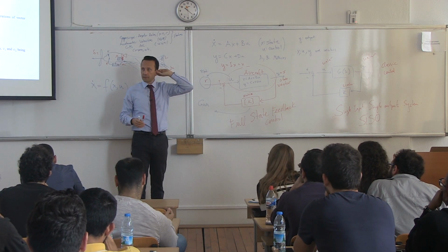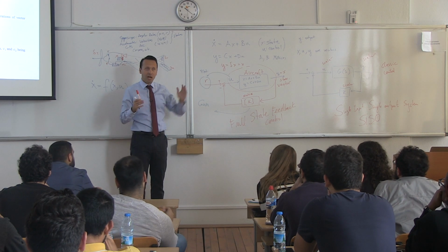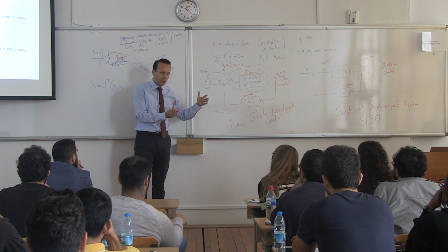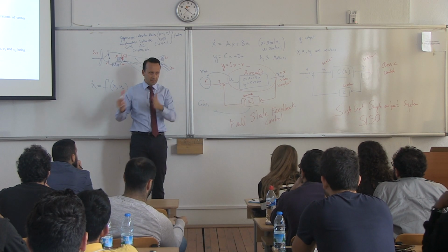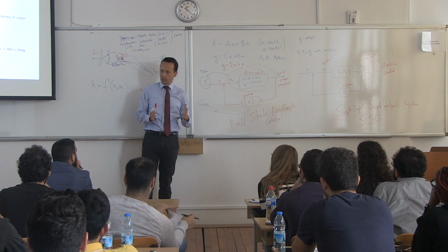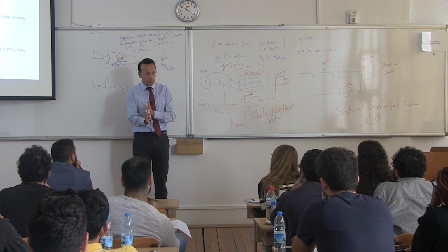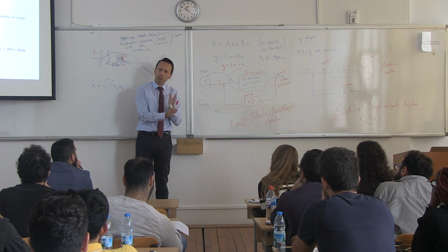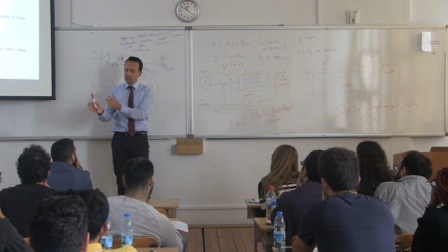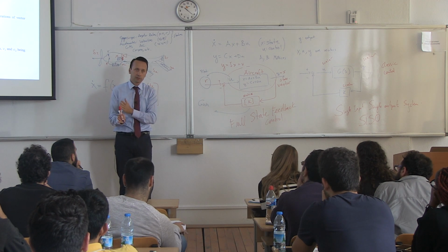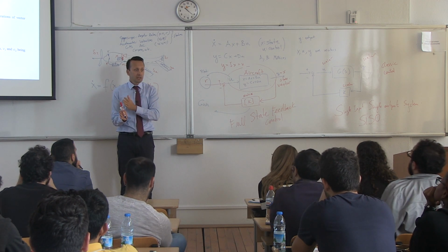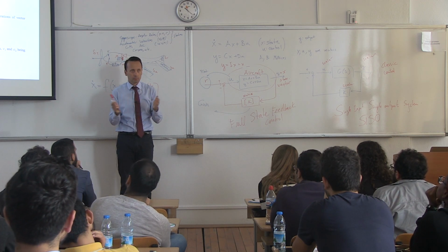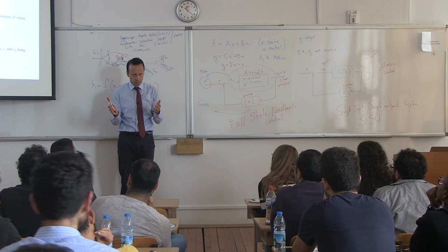So again, if you have taken flight mechanics with me, you will remember how we obtained the linear system. This is kind of a continuation now. We obtained the linear system in flight mechanics. We started with nonlinear equations. We chose a trim point, remember, which was an equilibrium point. And then we linearized everything around that equilibrium point and obtained this linear matrix, this linear system. And this linear system was only valid in a closed neighborhood of the trim position, of the equilibrium position, right?